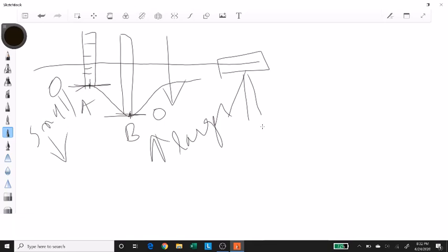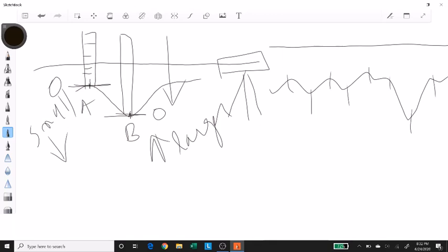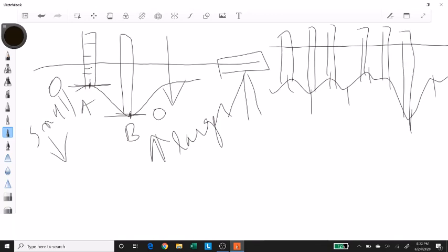By using this instrument, you can quickly find out height difference between a lot of points. So if I have a very difficult terrain, I can just place my instrument at one location, and this becomes my line of sight, and I can find out heights of different points just by taking my staff, placing them at all the points whose elevation I want to know without moving my instrument. So this really speeds up the process of finding out height difference between different points. So once you have all of these values, what you can do is you can draw the profile of the land,